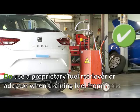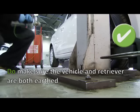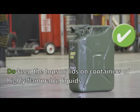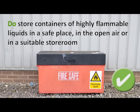Do use a proprietary fuel retriever or adapter when draining fuel from tanks and lines. Make sure the vehicle and the retriever are both earthed. Do drain fuel outdoors or in a well-ventilated area. Do keep the tops or lids on containers of highly flammable liquids. Do store containers of highly flammable liquids in a safe place, in the open air or in a suitable storeroom.